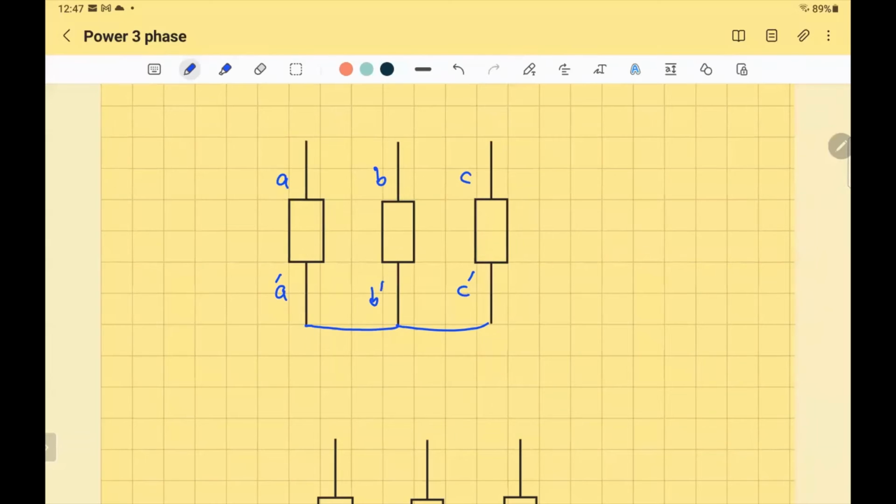So this is how you connect it. And these are the terminals that, if you want to supply current, you connect to the source, because you have a three-phase source. Then you connect this to the source, because most of the motors and generators in industry are three-phase. All big motors are three-phase. And the input will go there, to the ABC.